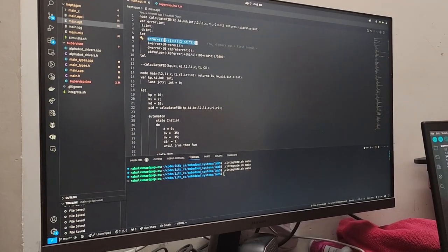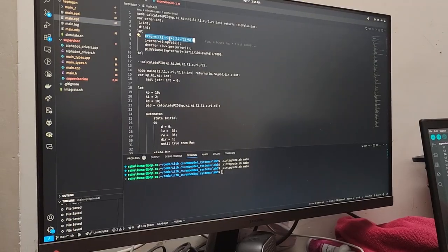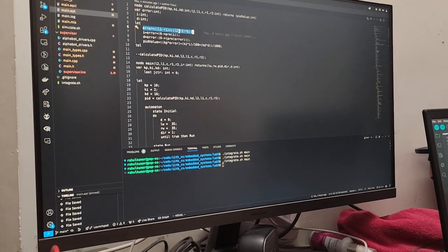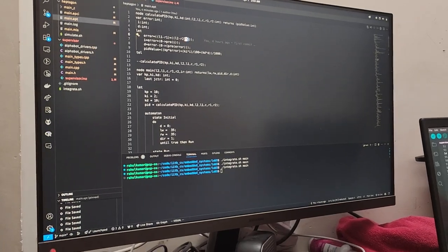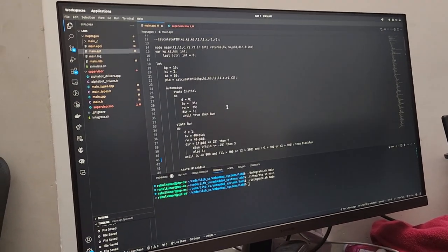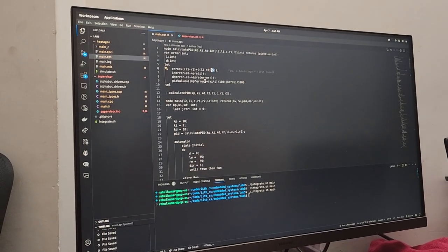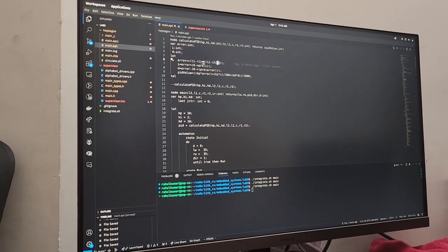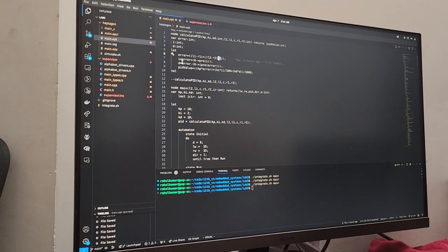So it's left minus right, the left sensor value minus the right sensor value, and the extreme sensors are being weighted by 5, and this is again a calibration constant. All the numbers that we have used over here are basically calibration numbers, so it depends from machine to machine and lighting conditions and the code also.